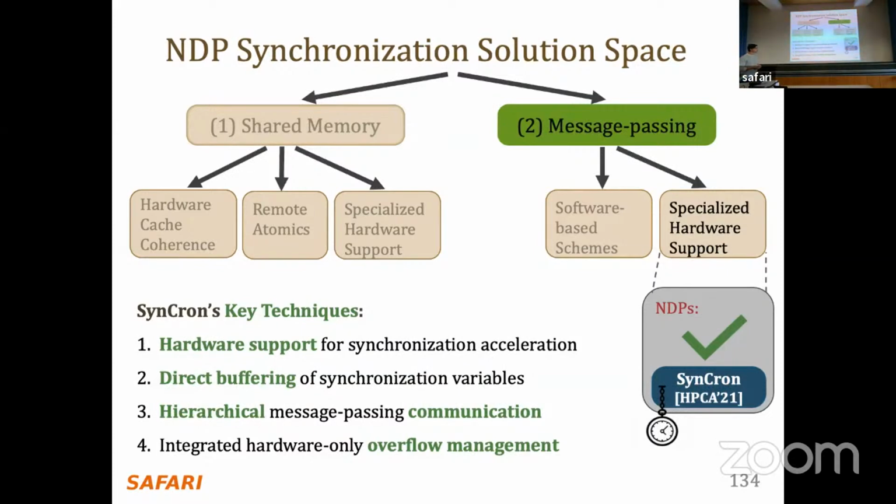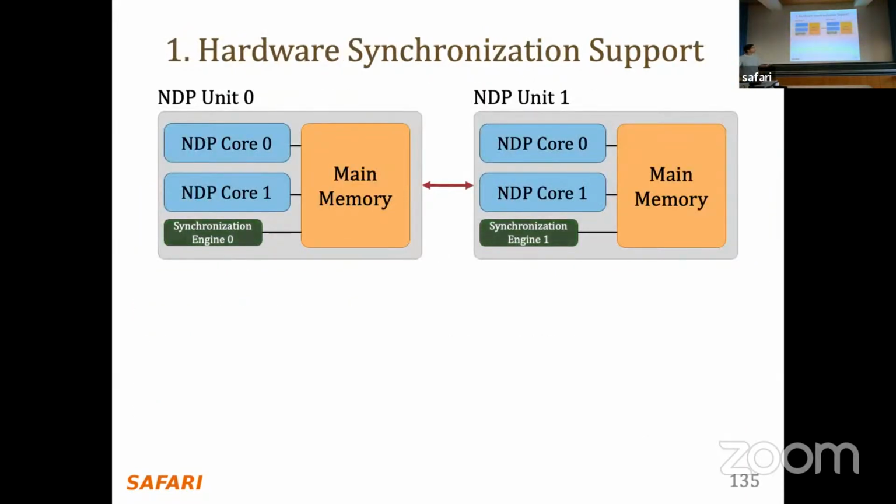What SynCron provides is hardware support for synchronization acceleration, direct buffering of synchronization variables, a hierarchical message passing protocol, and integrated hardware-only overflow management. Because sometimes, as you will see, there are some queues, and sometimes these queues may overflow, and there is also a mechanism to deal with that.